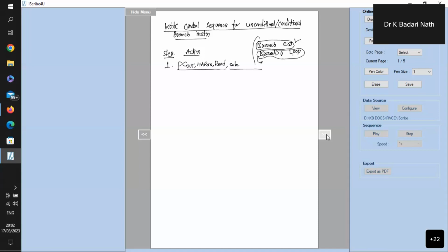Along with that, we get the program counter ready to add 4. That means select 4. Instruct the adder to add 4 to the program counter, and store the answer in the temporary register Z. These are the two operations we know. Now the result that is there, the added value, is put back into the program counter. This is standard.